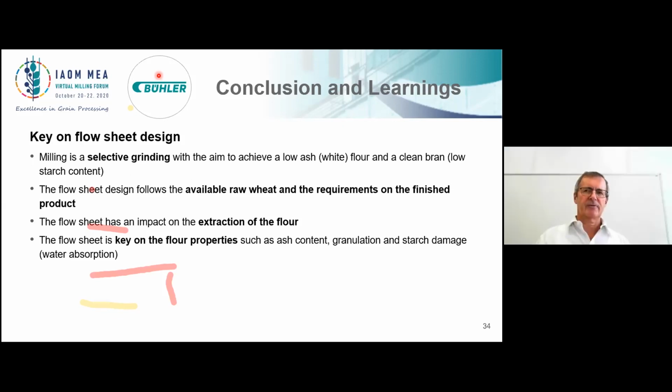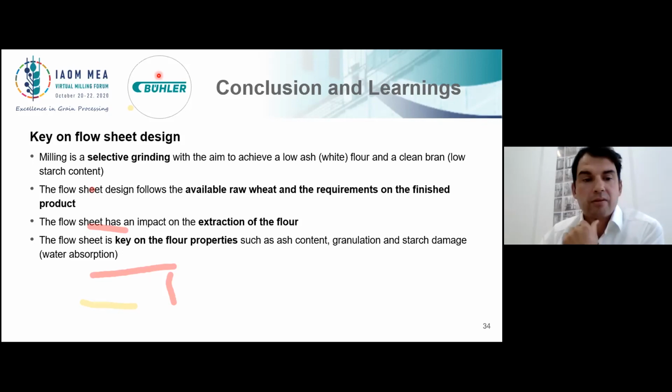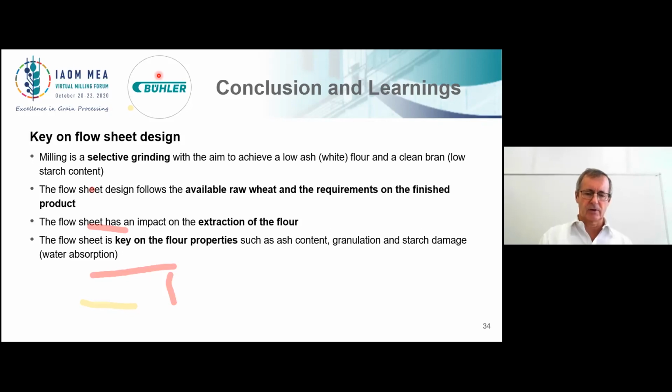When we talk about sieve number, is it the sieve opening or the total number? Usually, when we talk sieve opening, it's all about the end product. We know we have different demands. So the rule is if you have a good baker's flour, it should be finer than a home baking. A baker's flour is below 150 microns. A home baking, which is just used for pastry, can be 180 microns. You have pasta flour, 212 microns. So this depends on the task and application of the flour.